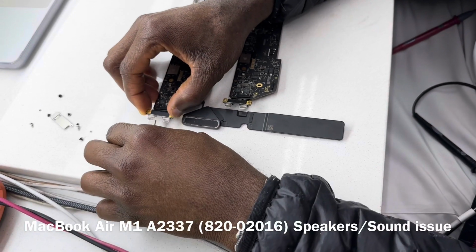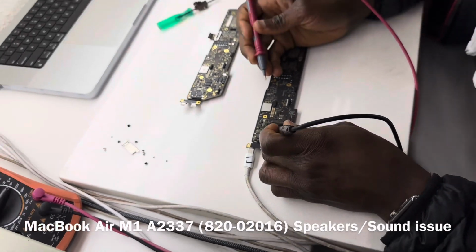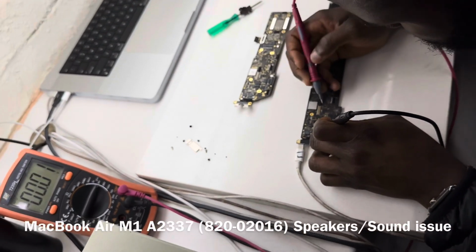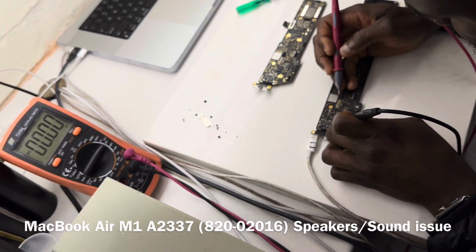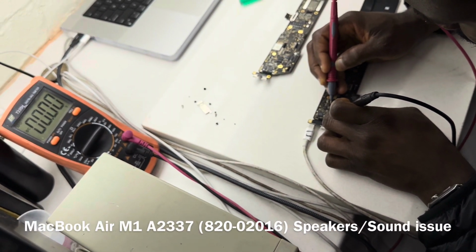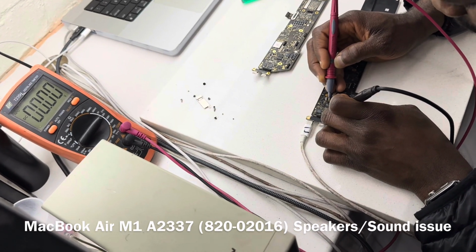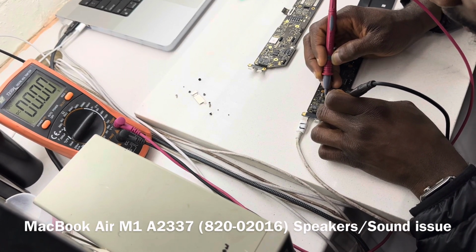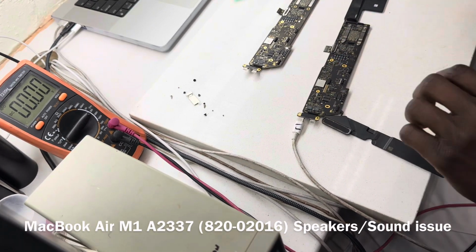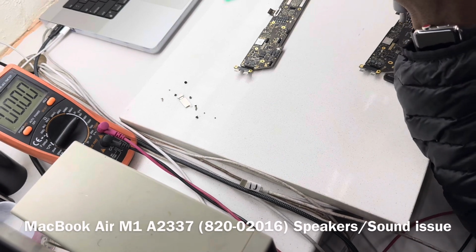Let's see what we measure. We've already confirmed that our speaker reset L signal is not low. So let's see here, measuring the same place, and we have 0. So what we quickly want to do is replace UR600 and see if we have any changes.